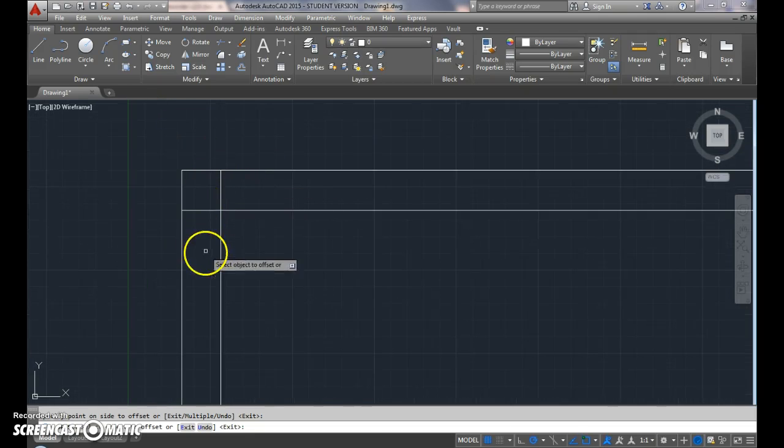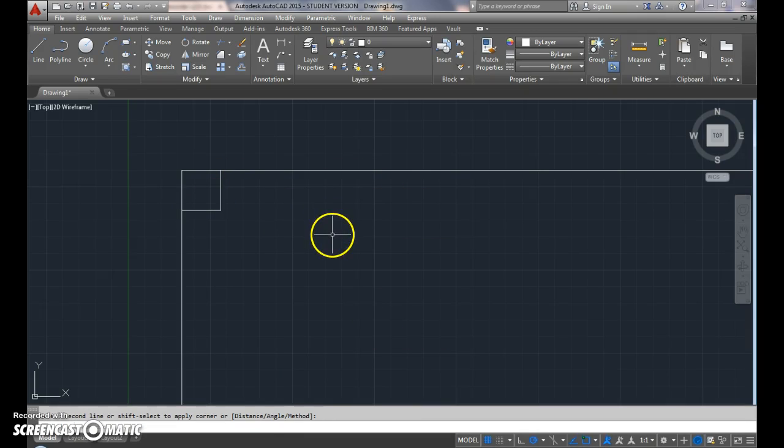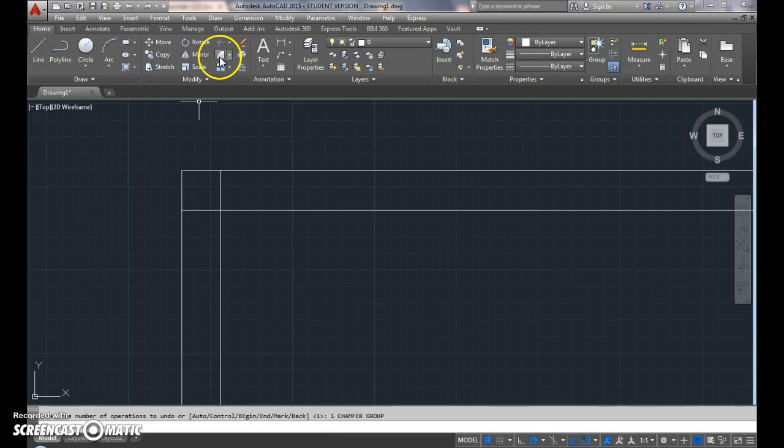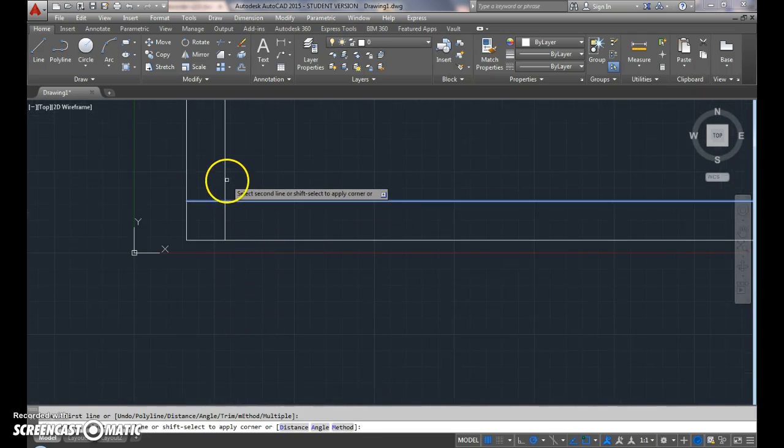One of the things I want to do is show these walls as being interjoined. And to interjoin those walls, it's simply a matter of going through and cleaning them up. What I do is I use the chamfer tool to do this. And you notice at the bottom of the screen here, the chamfer distance is set for 0, which means when I use the chamfer tool, it's going to make it a 0 by 0 setting. And I actually did that incorrectly. Let's try this again. There we go. And that will erase those corners. I'm going to do the same thing here.